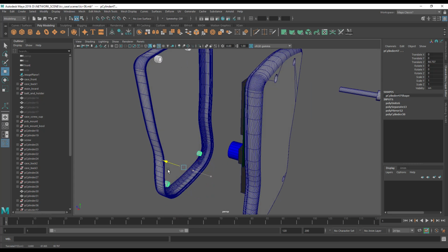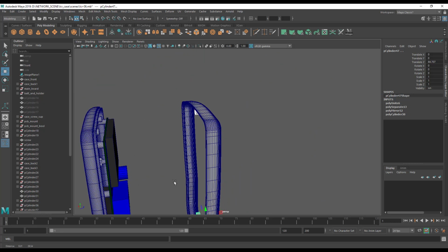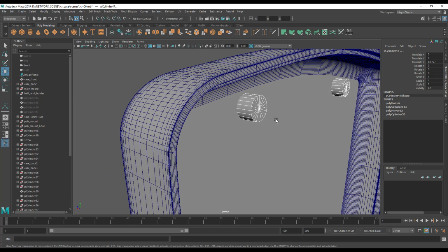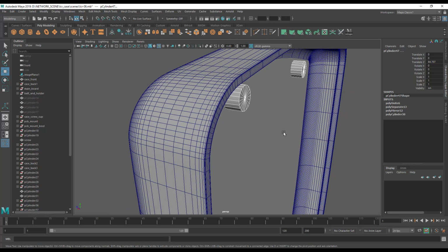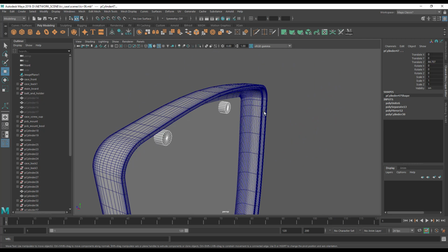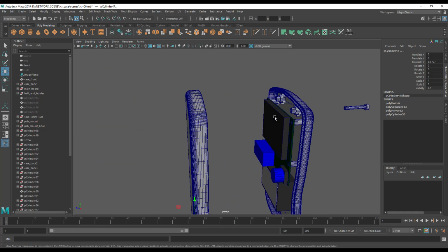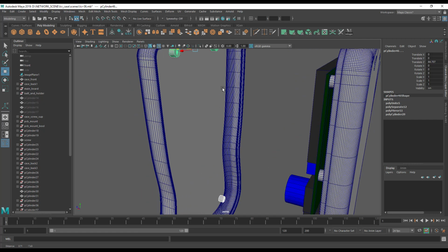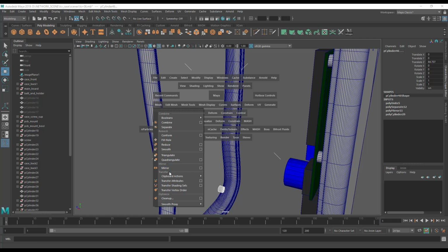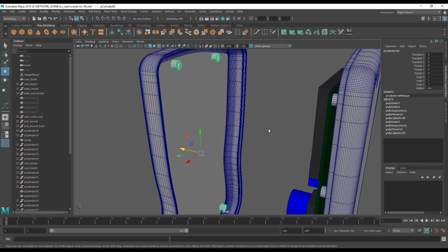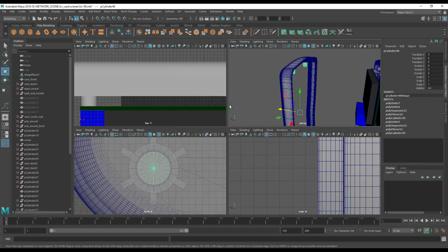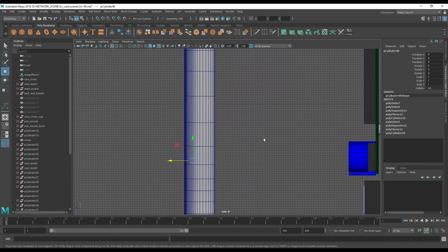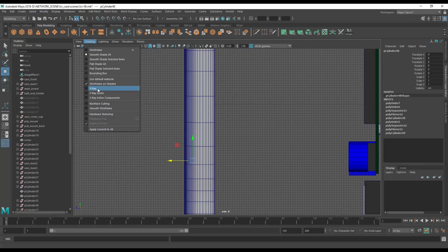Now we do not need to punch any holes through the front of this case, simply because we don't want to in this particular instance. Now we need to come out here and we need to select these and have them go to the inside marker of the case this time, not the outside. That way they should marry up when we move them over here. So let's combine them, all objects together. So mesh combine, just so we can do this all at the same time. And yep, sometimes Maya has a little conniption where it doesn't actually combine the objects for whatever reason. It's not feeling like it on that particular day, I assume.